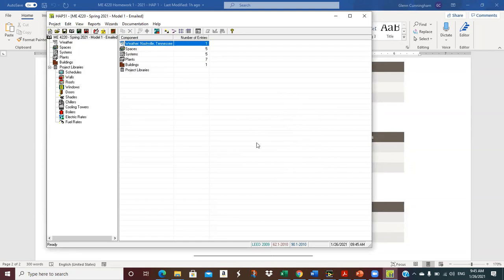Next time I fire up this program, I won't go to retrieve. I'll just pick it out of that list, click it, and bingo, it'll be there. But if you want to email this model, you have to do the archive, because it includes all the weather files and a bunch of other files it has access to on your computer. If you share a model with somebody else, they may not have those files if you just send the saved version of the file.